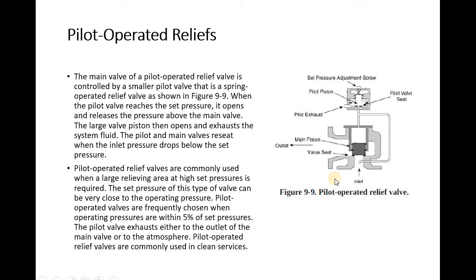There are other operated reliefs called the pilot operated relief valve, and again, you're pushing here. I may not go into the details of this because it has a complex operation, but you can see that there's a spring here, and we also have a large piston at this side here. It helps with balancing the pressure as well, for the valve to sit perfectly in its place.